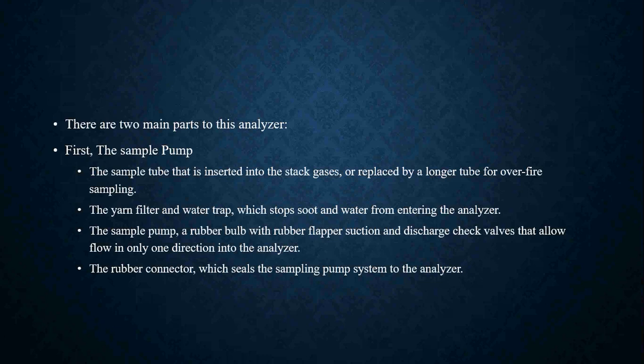And that type of tube, if you're really going to do a CO2 test over the fire using this, literally needs to be about 30 inches long in order to really get a good CO2 reading over the fire, because the tube has to technically reach all the way into the center of the combustion chamber, because that's where all of your CO2 is going to be pretty much at its highest.